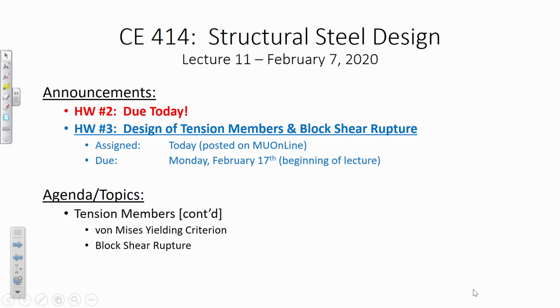Now, block shear is a little unique. The equation is very, very complicated, and I will tell you, you don't really design for block shear. In a design problem, you do what we did in the last example, design according to yielding and fracture. Block shear would be something you just check later. The reason why is you're going to see the equation is very, very complicated. There's no way to just solve for the area. It's a bit messy, so you just have to go through it.